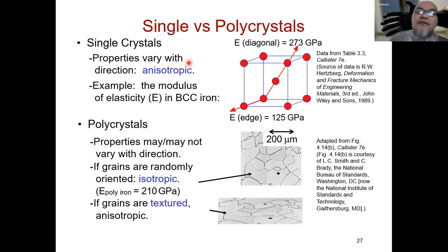In the 110 direction, the side diagonal, sorry, in FCC at 110 the atoms are touching each other, while in 111 they have space between the atoms. This makes different mechanical properties in different directions of the crystal. That is why we call it anisotropic material property.